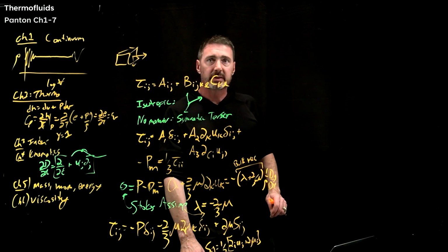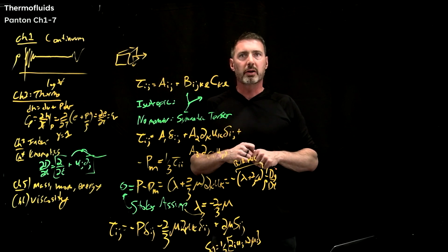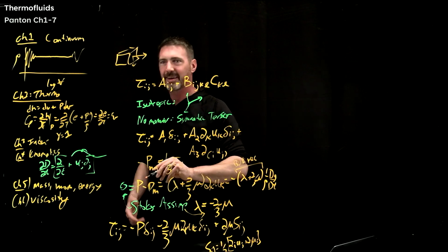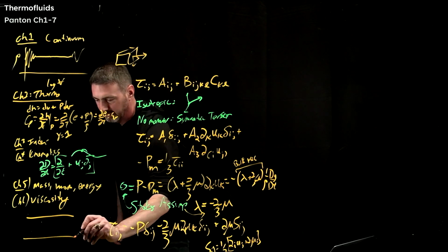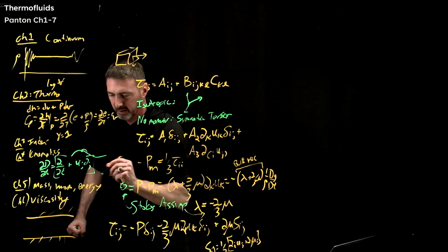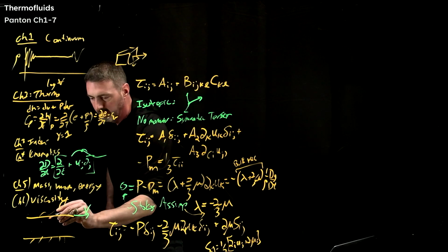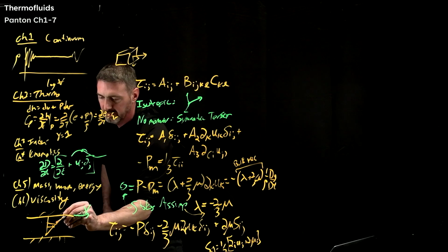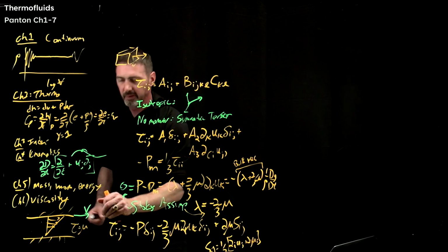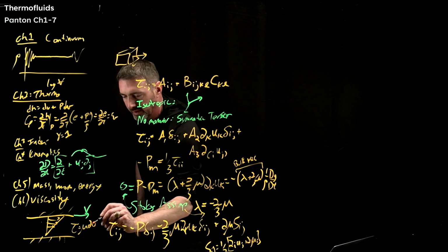And so again, this is true for compressible flows, and you can see why this was not done in undergrad. In undergrad it was just easy, basically stopped with this, and I'll redraw because we're going to talk about it, where you have a fixed wall and you have another wall. This top wall is being pulled at some velocity, capital V, and so your fluid flow is linear, and that's basically where we got to, and we knew the stress on that, because if you're actually running this experiment, you could measure the stress, and it's related to that gradient,